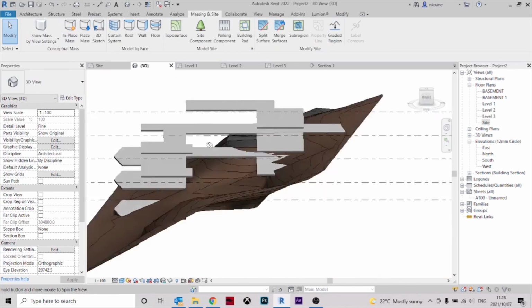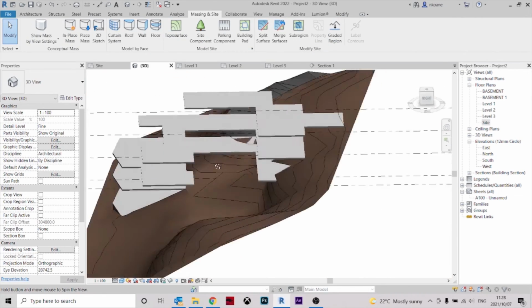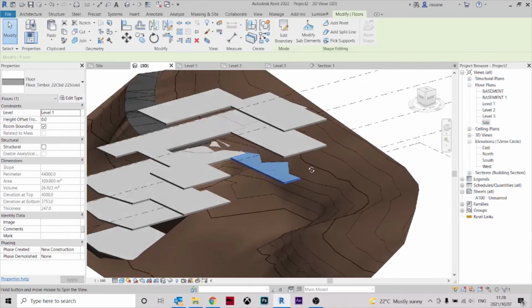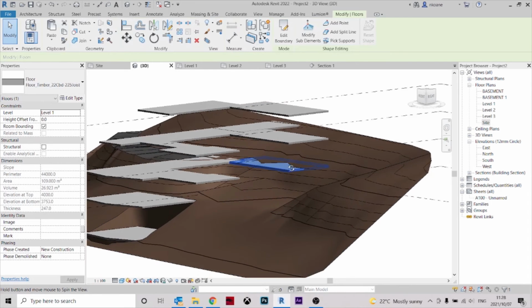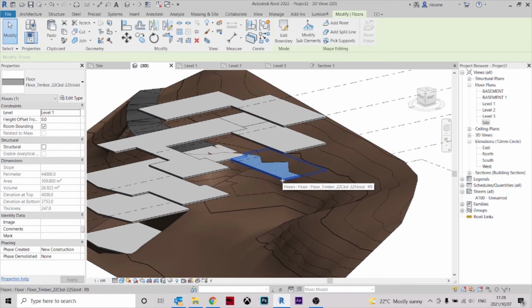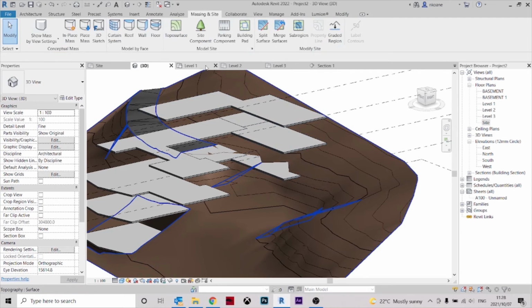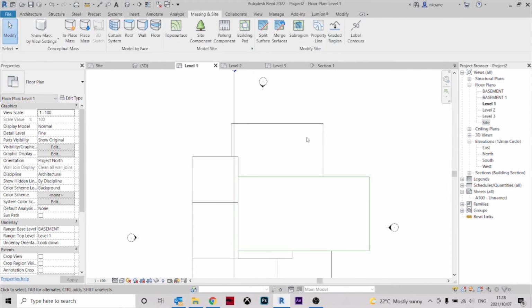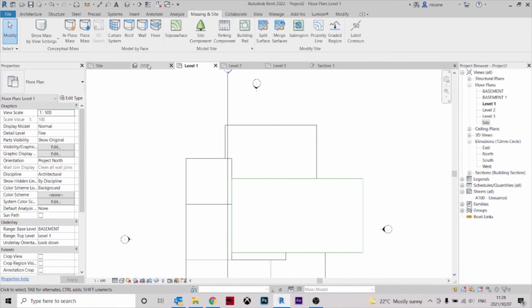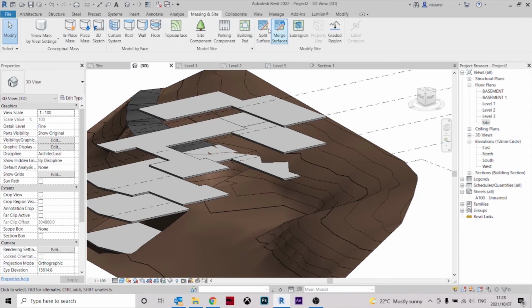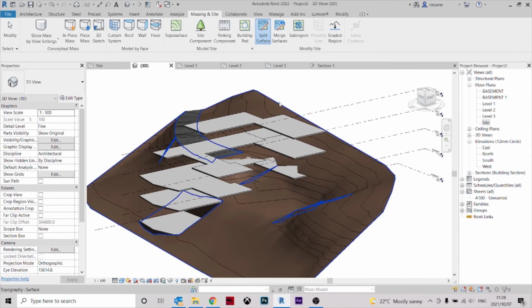At the end of the day, they will achieve the same thing that you would want to achieve, which is to create a hole in the space, but this is all about choosing the easiest tool, or the easiest method. So if you go to 3D and you choose a split surface, this means that we are going to split the site into 2 surfaces.